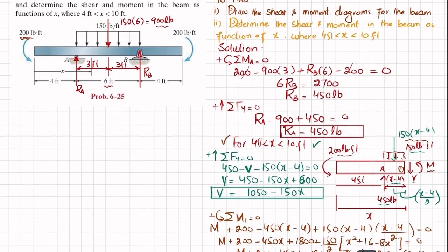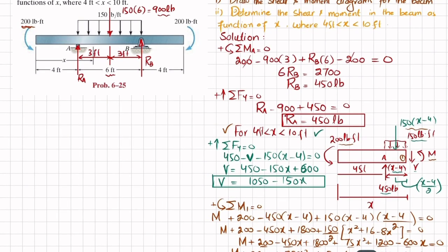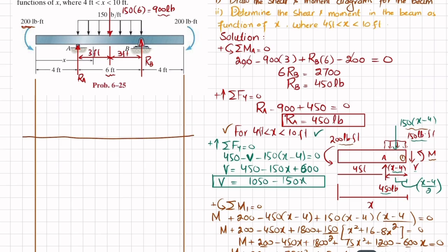For that I will take vertical lines from the ends of this beam. Clear? Let me take it, and we will draw a horizontal line in order to show the shear force. X will be in feet. On the y-axis we will take shear force, in pounds.